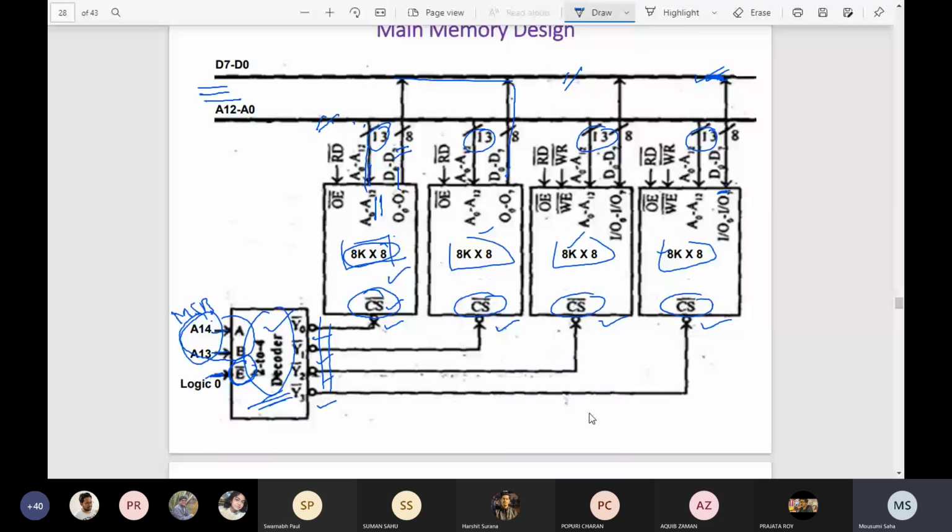And suppose that if you need more than that, suppose you have the 16 address lines, so on that moment you also have A13, A14 and A15. So 13 and 14 you can use for the input of your decoder, and other lines you can use to enable the decoder. Okay, so sometimes it may happen that I take more lines, suppose that A16 is also available.